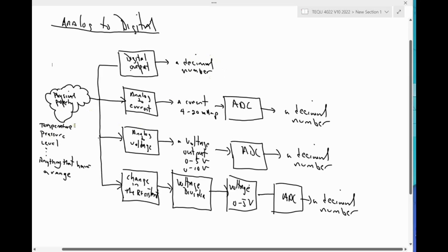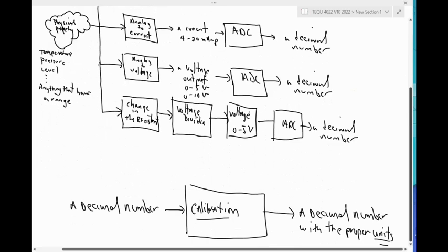If it's temperature, then centigrade, Fahrenheit, Rankine, and so forth. Pressure: Pascal, or PSI, or PSIG. Level, whether it's going to be centimeters, meters, gallons. You have to be sure that the physical property is eventually read with the proper unit as required. So this is the final step that you need to do in order to get that.